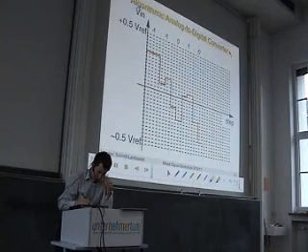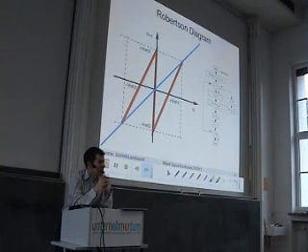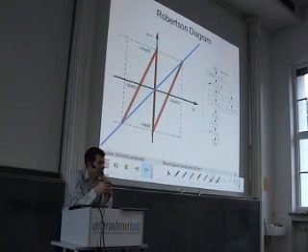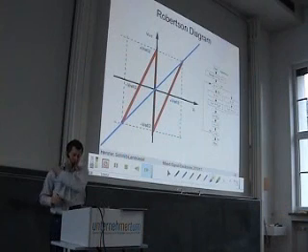Let me give you another illustration of this algorithm, which some people call a residue plot, which is also known as the Robertson diagram. It is simply a graphical illustration of this algorithm, but an illustration that helps you to understand the problems in a converter and that may help you to understand the operation.